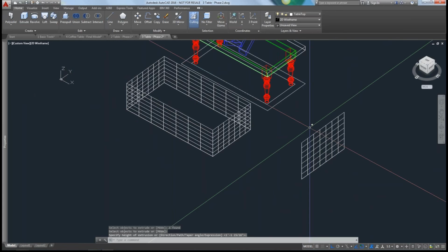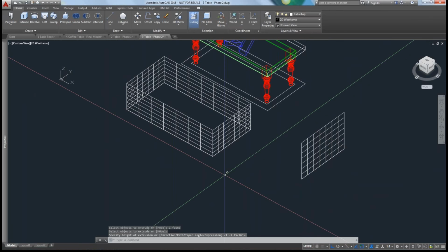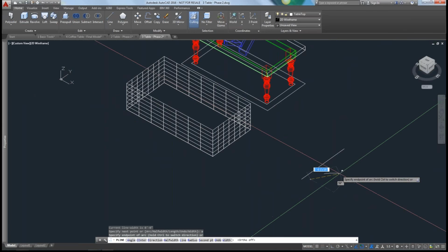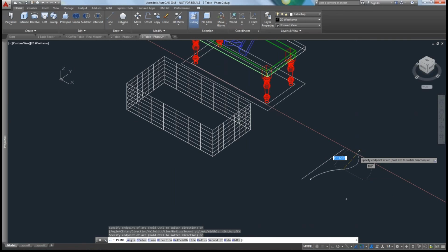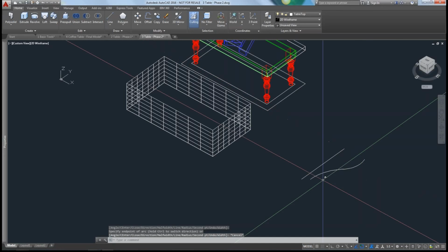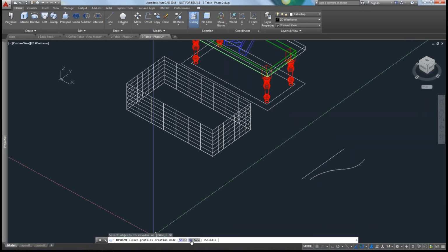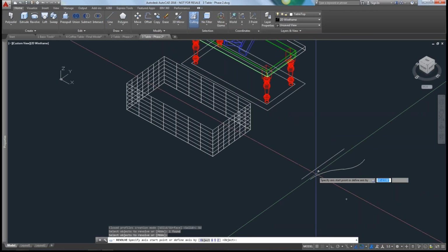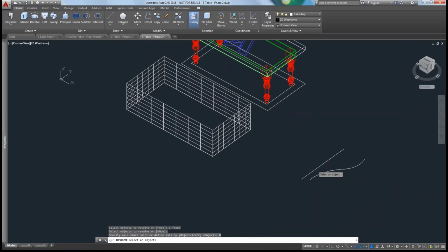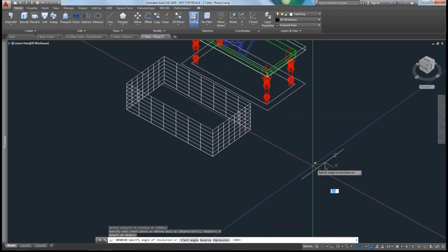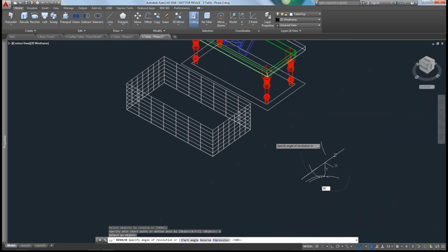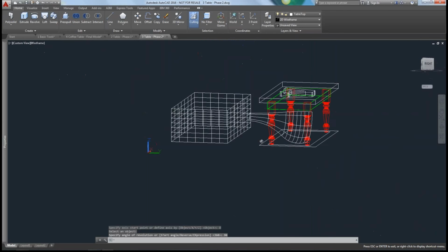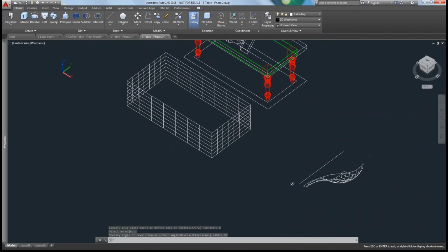Now, let's say I use a polyline command along with an arc here. Bear with me one second. And we want to use the revolve command. Again, it has the mode on the bottom. You can use a surface, selecting the object, and then the center line, and revolve it into a surface. Let's do 90 degrees here. You can see how that shoots over to a surface. The surfacing commands, there's a lot of them. They get really in-depth.